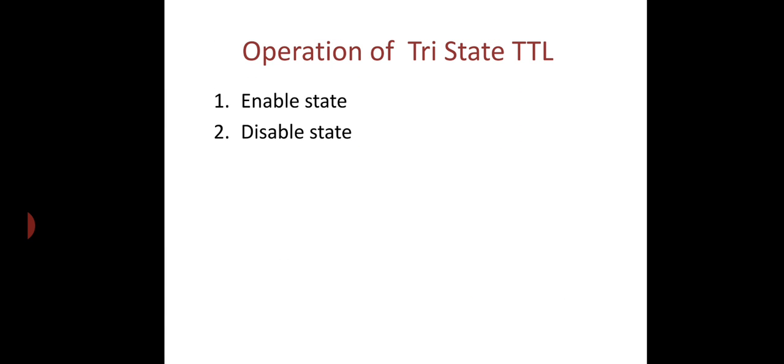So we can say the enable state, that is E, can produce the high impedance Z. Therefore, when E, the enable pin, is at high, that is at logic 1, the gate is enabled and behaves like a normal inverter because high voltage at E has no effect on T1 or transistor T2. So in this enabled condition, the output is simply the inversion of logic input A.